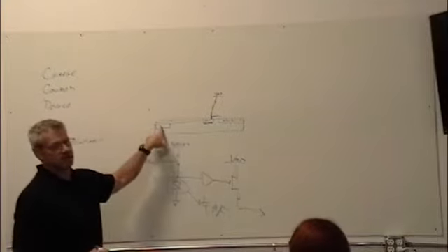Problem number one. Now you can get around this. There's ways to get around this. They've always used these for infrared detectors, once they got to the point where they made what we call a ROIC, a readout IC. If you look at it from the side, sure, it's only got this little spot, but what they do is they put a bump bond on there. And then they put a big thing like this on top of it. And that is an expensive process, because you have to align these things, right? I've taken a piece of material here that is all these diodes, and now I don't have a diode. It's got a connector here for a ball bond to go onto.